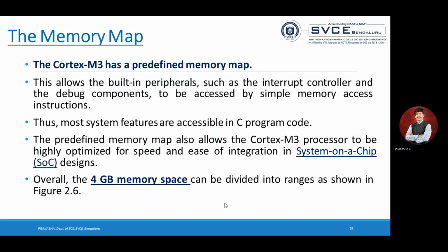Usually we write the program in C, then we execute it. At the time of execution, we give the instruction to convert or generate the hexadecimal file. That means it will convert the actual C programming into your microcontroller programming. It will be in assembly language. Then once the assembly language program has been converted, we are going to dump it to the external peripheral that we have connected.